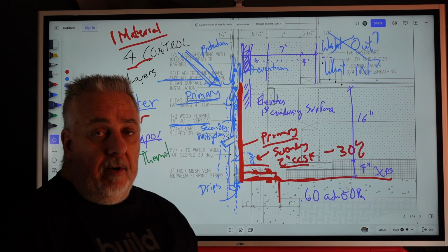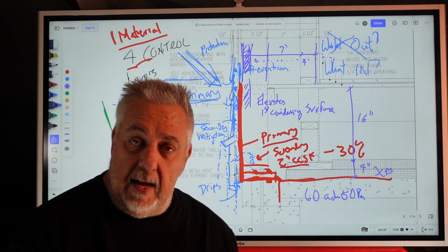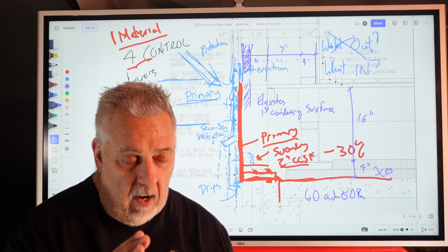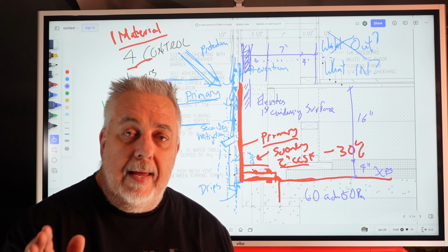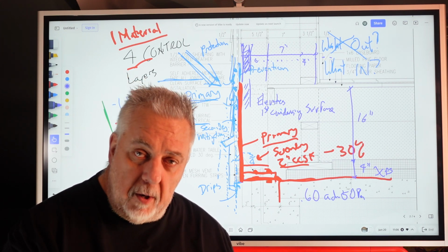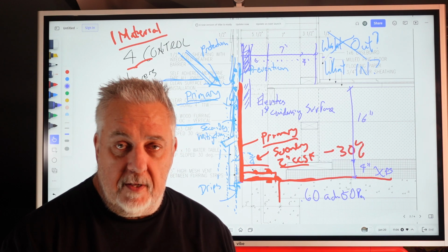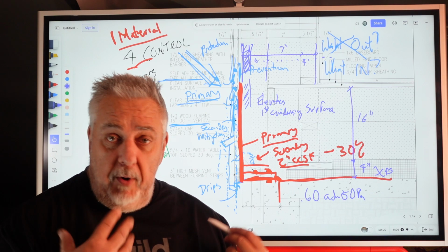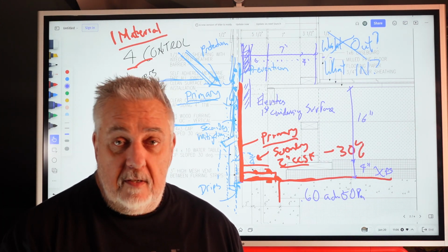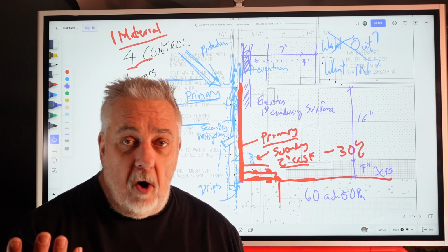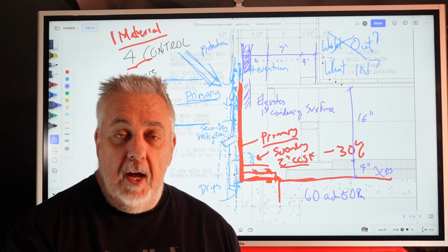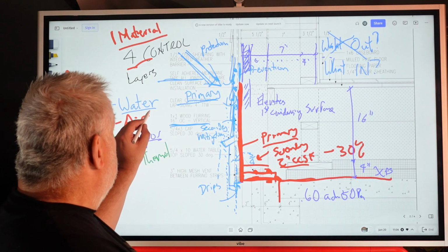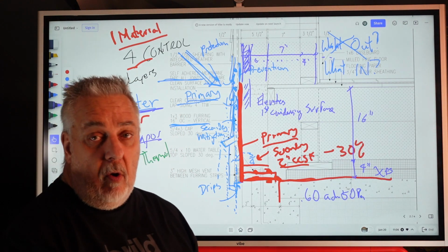And elevating that first condensing surface means elevating it in temperature, so that we're a lot less likely, almost at no risk, of getting a temperature where vapor diffusion is going to find a cold enough surface to condense. And if it stays as vapor, who cares? I'm breathing in air that has moisture in it, right? It's vapors all around us. It's no mystery. It's when it condenses and becomes liquid water that we have a problem.